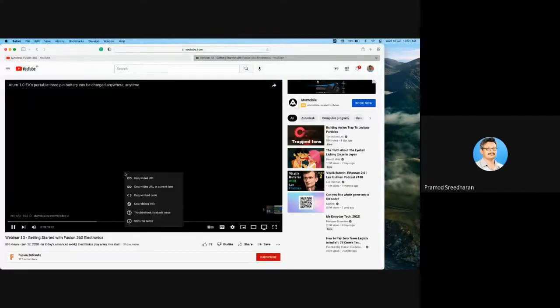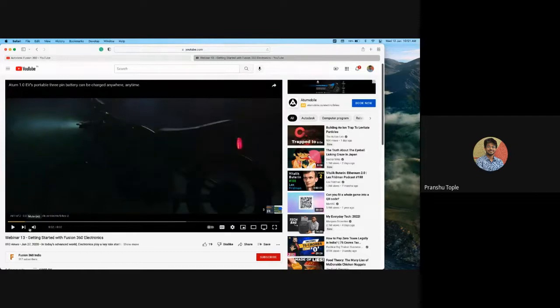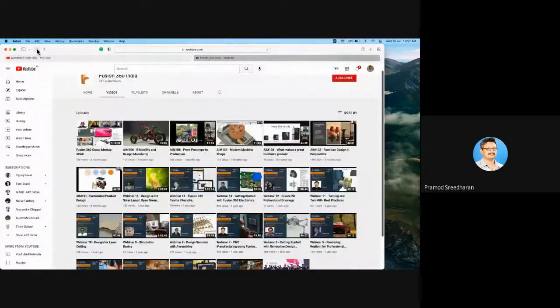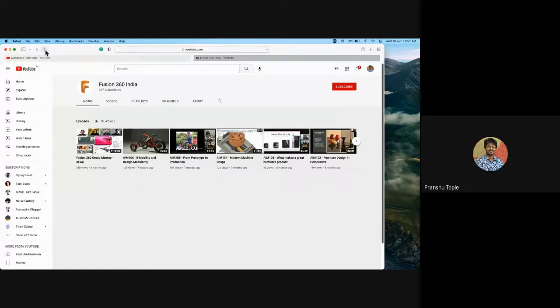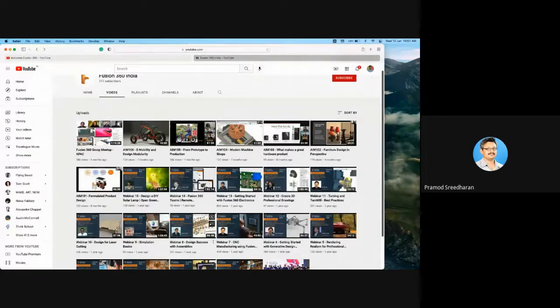Sir, I think that is an 8-link strand beast design. He made a strand beast on the seashore. Yes, it is called strand beast. It is an 8-link mechanism design. So it's based on Theo Jansen's mechanism, right? Yes, correct. I was not remembering the name. Because getting an 8-link design for single degree of freedom is extremely complex, and he somehow cracked it. Till now, I could not figure out how he did it.